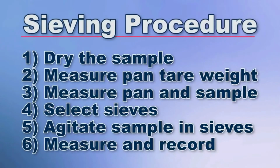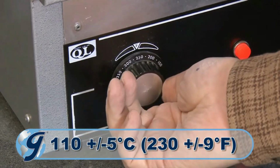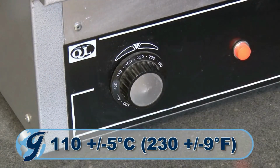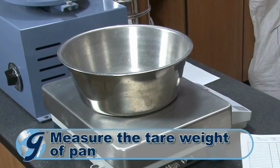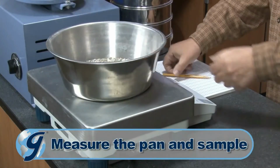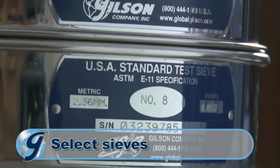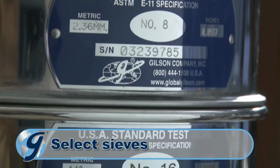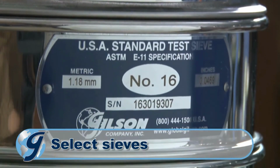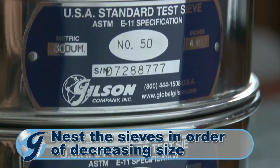For the procedure of the standard test method for sieve analysis of fine and coarse aggregates, we first dry the test sample in an oven at a constant temperature of 110 degrees Celsius. Measure on a balance or scale the tare weight, or unladen weight, of your sample container or pan. Now place the test sample into the sample container and measure its gross weight. Next, select test sieves with suitable openings to furnish enough information required by the specifications covering the material being tested. Nest the sieves in order of decreasing size openings from top to bottom.